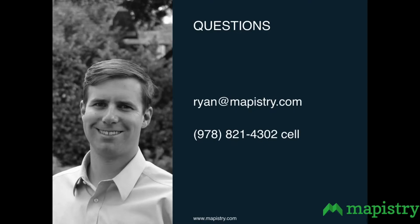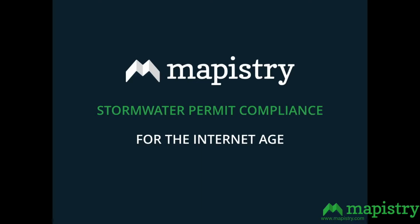In terms of biggest issue, collecting the samples, how do you do it in the middle of the rainstorm to get enough people out there? Accurately collect samples. TSS, big problem. Number one thing on sampling in TSS that we see is people collecting samples that they scrape the bottom. So if you have staff that's responsible for sampling, tell them to go get a sample, they go out there and they scrape the ground surface, or they sample a puddle, or they stir up some sediments. If it's out of a catch basin, they scrape the bottom, they drop it down on a stick and scrape up the sediments. All problems with sampling in TSS. It's not really your industrial process, it's your sampling technique. And that's what we find.